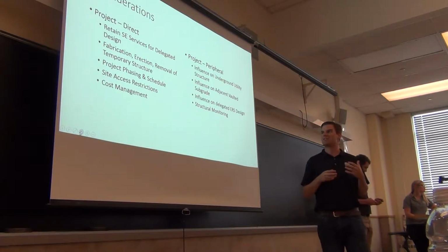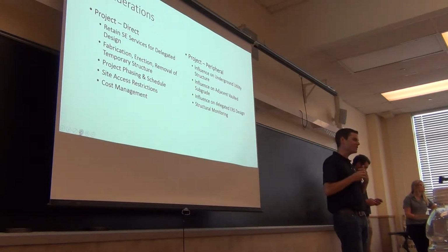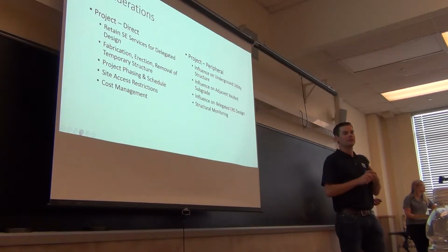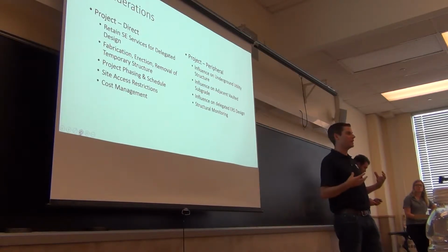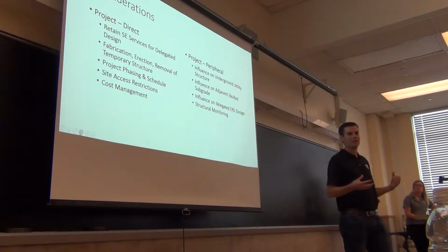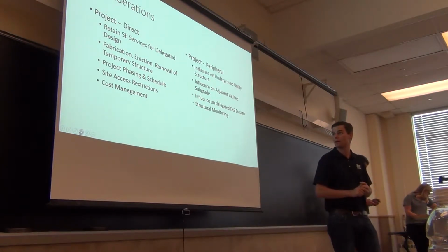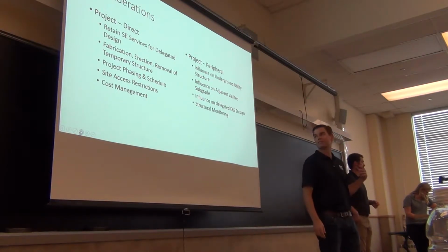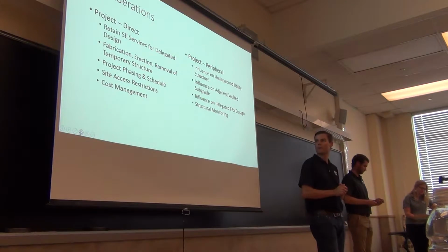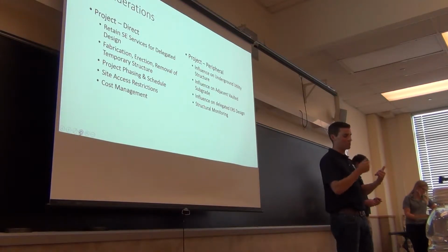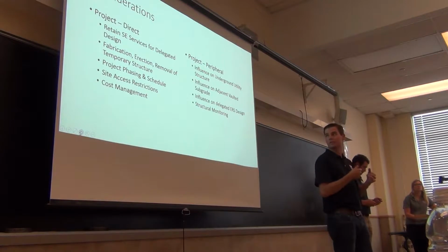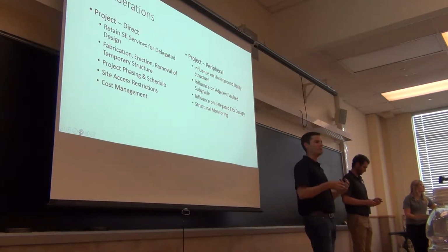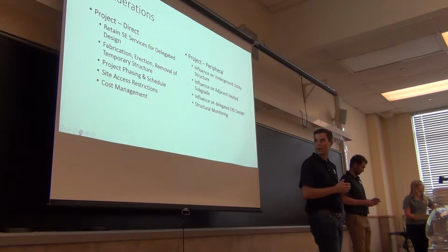I would say that the direct project considerations are, as soon as you see that delegated design, it's on us, the contractor, to design the temporary structure as a means of completing what's shown in the contract documents. We don't do that in-house. That's where we bring an outside SE on board to help us out with this. Then also you have to consider that once you've developed this temporary structure, you have to bring on a fabricator, a steel erector, and there's time and material costs with each step of that process.